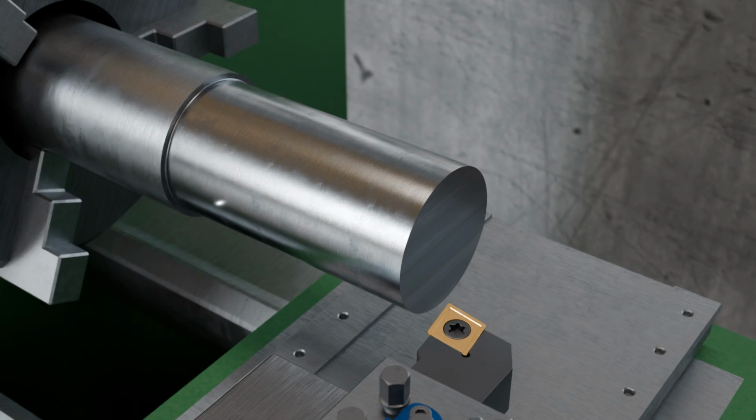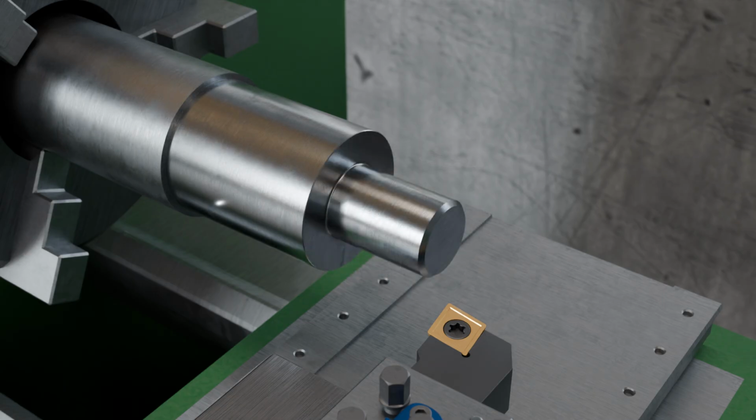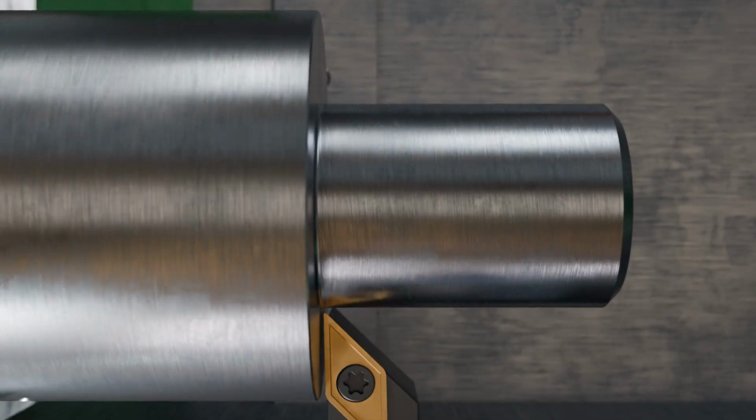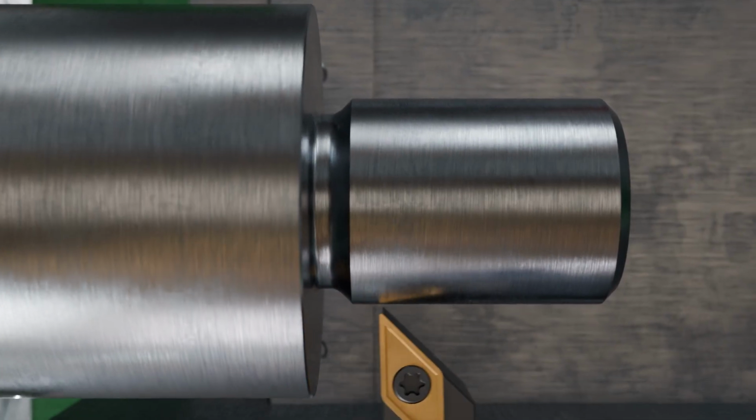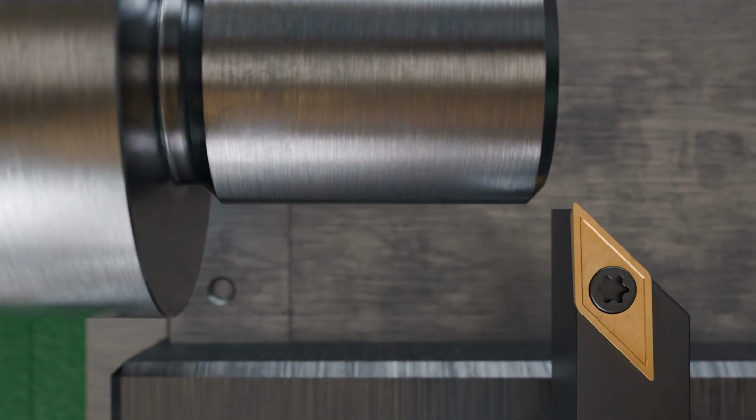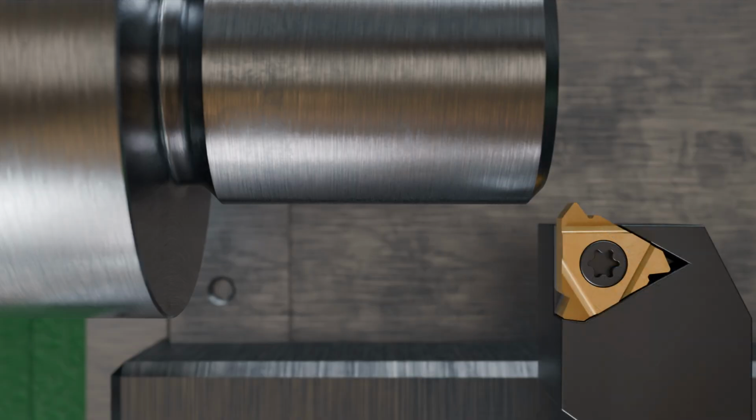Another turning method is thread turning. In this process, the shaft section where the thread will later be cut is turned to approximately the nominal diameter. A 45-degree chamfer to the thread root facilitates later screwing on of the nut. If the nut is to be screwed up to the shaft shoulder, a so-called thread run-out or thread relief must be made beforehand, allowing the thread to run out into the open. Very sharp indexable inserts are used to machine the thread run out. The thread itself is produced with special threading inserts whose cutting edge has the shape of the desired thread profile.